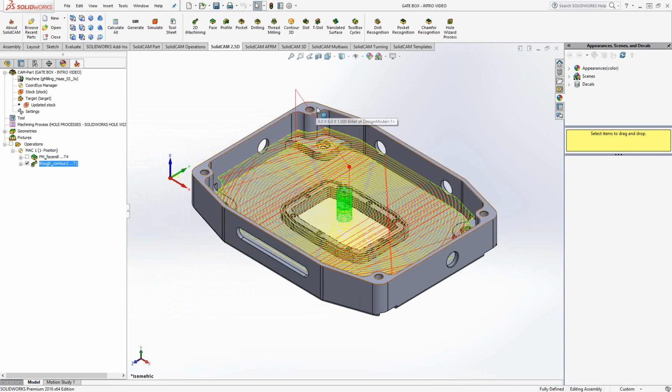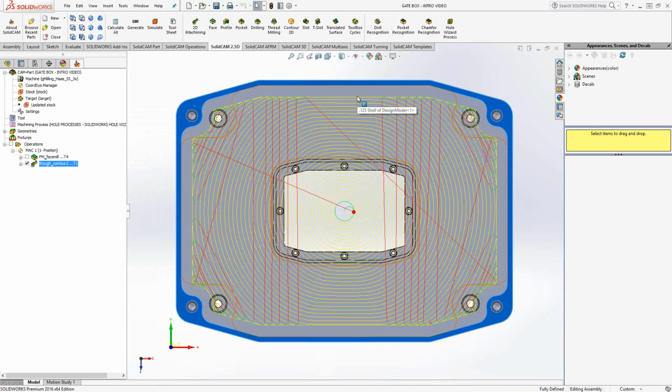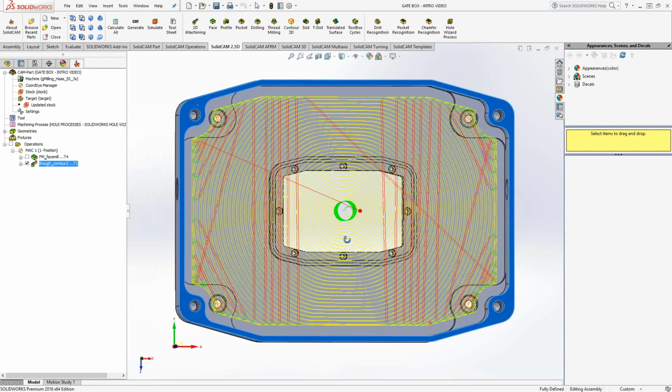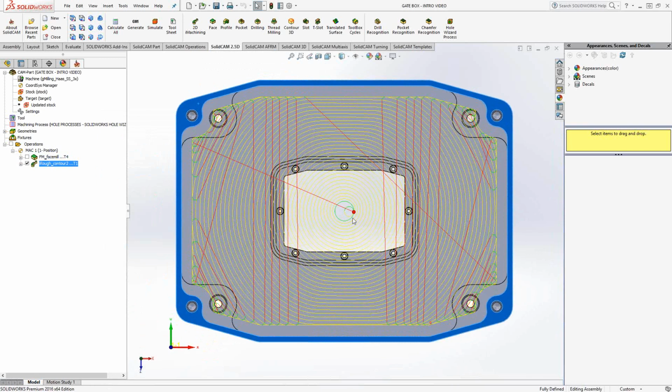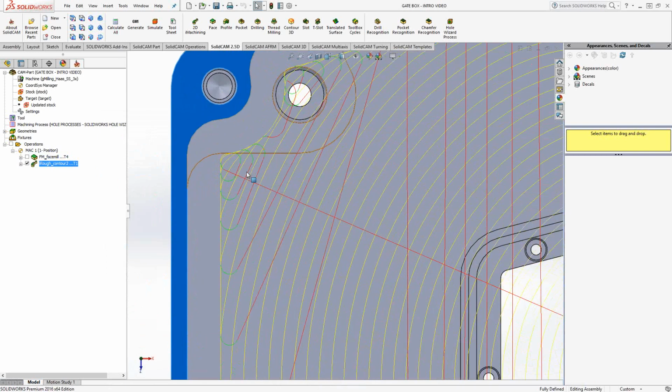Okay, so if I exit that, and let's take a top view of that. So iMachining begins with that helical entry. You can see they're represented in the green. And from there, from that helix, it morphs out in what we call the morphing spiral to match the outside contour of the pocket. But as it goes along, when it gets to these corners, it actually feeds out rapids and retracts back to a cutting area where it can actually re-enter the part with a better cutting angle. It's always regulating the feed, the speed, and the cutting angle to make sure that it optimizes the toolpath, in this case, in these sharp corners, to not bury the tool, to not overload the tool.